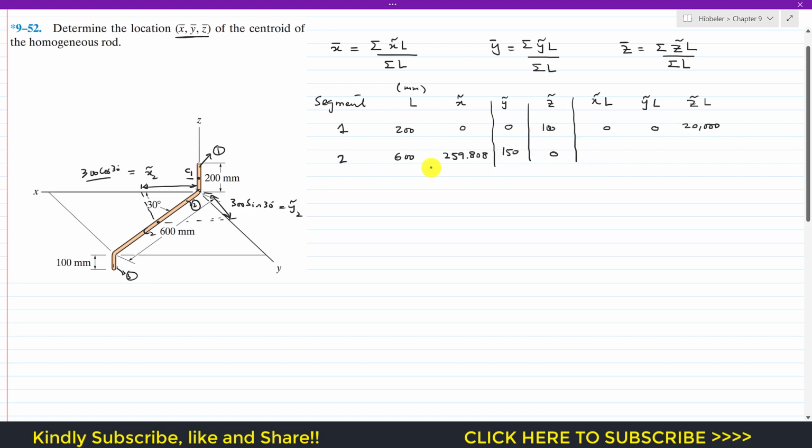Now we will take the product later. Now we will consider this segment 3. Its centroid is located somewhere here, let's say that is C3, and it is again at a distance of half of the length. This is at a distance of 50 mm, and as we can see, along this length it is at a distance of 600 mm from that origin. So again the distance of the centroid of this segment 3 along the x-axis will be this distance.